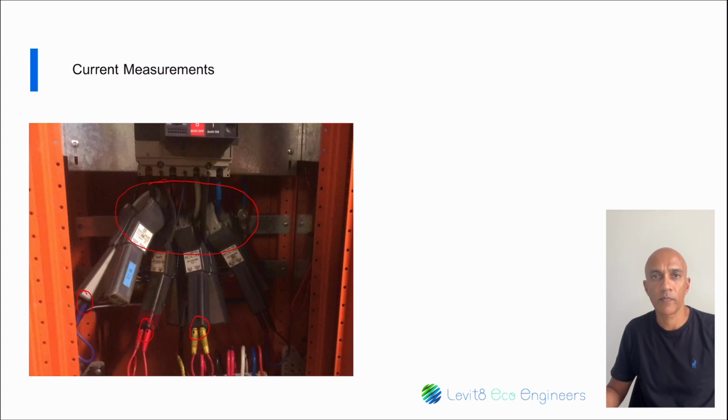the measurement. Now for load measurements, you would likely select a measurement interval of 5 or 10 minutes. This means that the instrument continuously measures in milli or microseconds for 5 minutes and then averages the data into a single 5-minute value. Now that's only going to give you an averaged value over the 5-minute period. Then you would probably also want to select the max values during every 5-minute interval to see if there are any long periods where the phase load is higher than the average load.